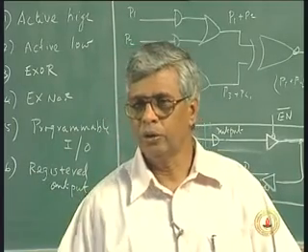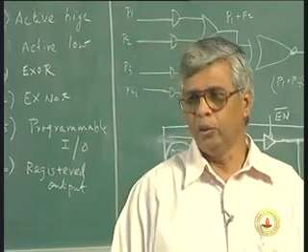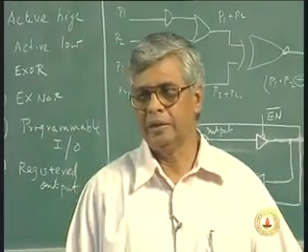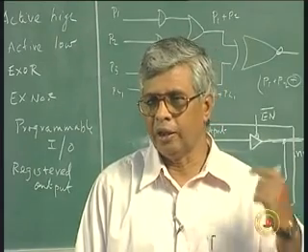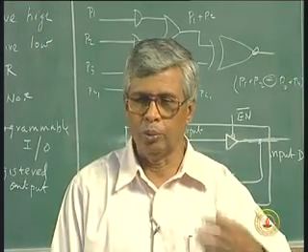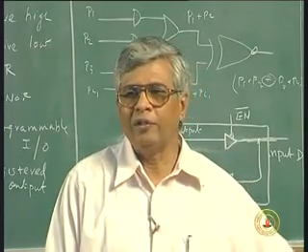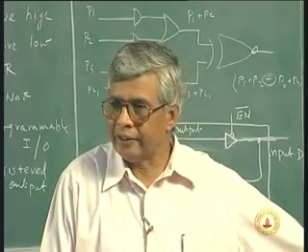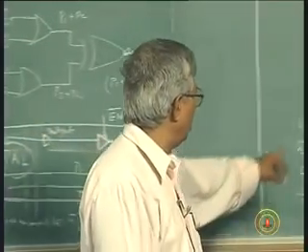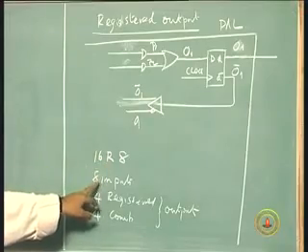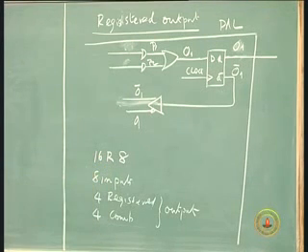So leave that out. ROM-based design, where required, they do it, the lookup table approach, but generally only when the size is small do they use ROM. That leaves two other alternatives, programmable logic array and programmable array logic. I told you programmable array logic is more popular. We usually consider 4 or 5 or 8 inputs, for example 16L8 or 16R4 is another example. 16R4 will be 8 inputs, 4 registered outputs and 4 non-registered outputs.